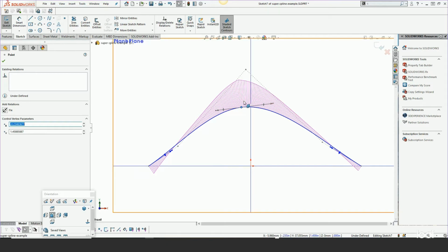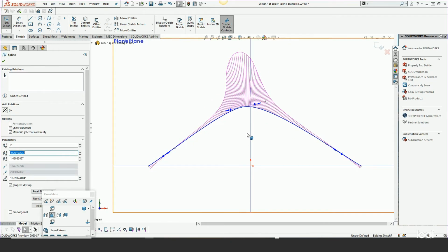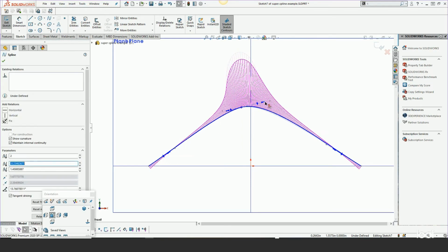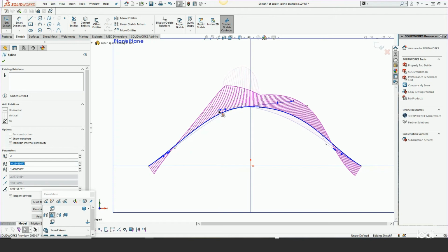So if you are going to do 3-point through splines, it's best, in the interim curves, to hold down your Alt key. By holding down the Alt key, you're able to drag these symmetrically around that interim vertice, and you're going to get the best result that way. If I let go of my Alt key and I start to drag these individually, you see what happens? You get something that doesn't look quite nice and is not a desirable effect.